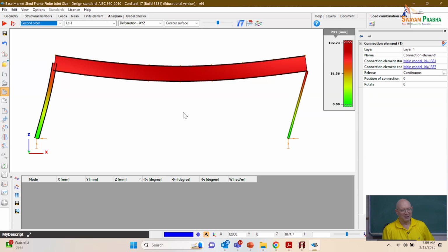But again, what we did yesterday, I was putting that pin at the center line of the beam. So if you run with that for a minute, what do you think changing this model, where I shifted that pin connection to the girder down to the bottom of the bottom flange of the roof girder, is doing in terms of the mechanics of what's happening here in the structure? What do you think?